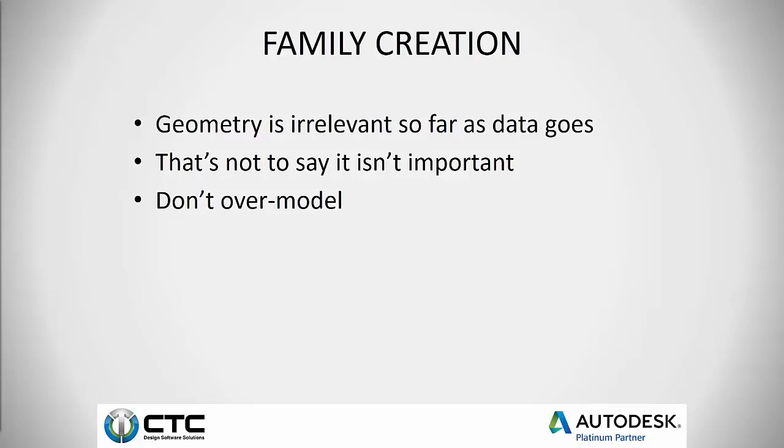The other key thing is do not overmodel. Overmodeling, if you're, say, using something many times within a project, maybe it's a light fixture. You don't want to model all the little fins in the louver. That just bloats your model and makes it pretty difficult to use.